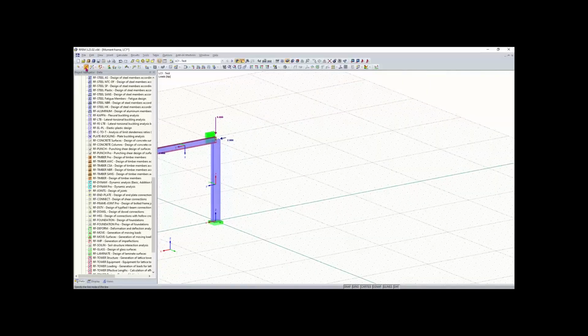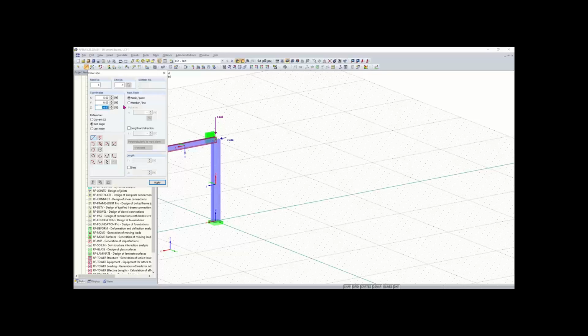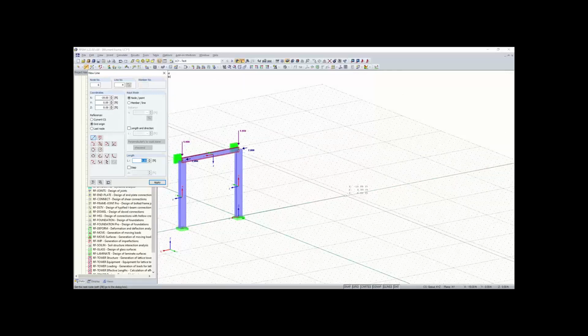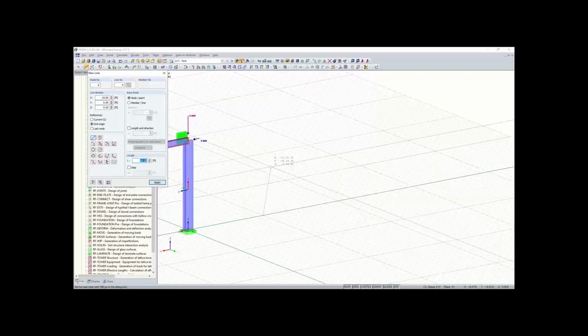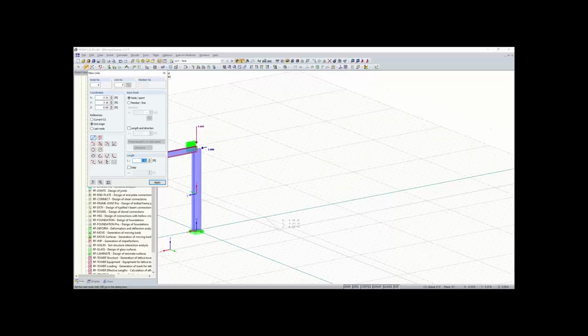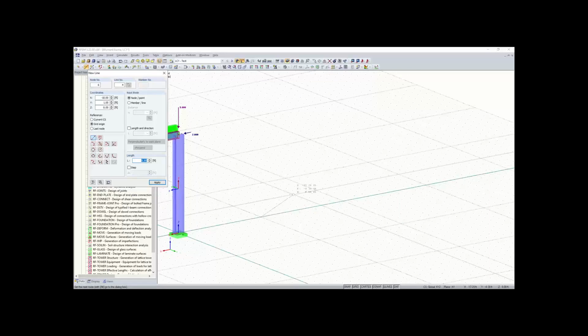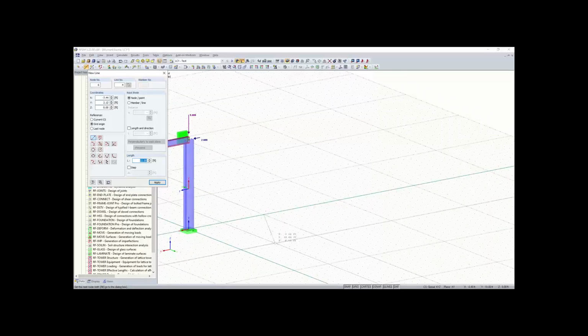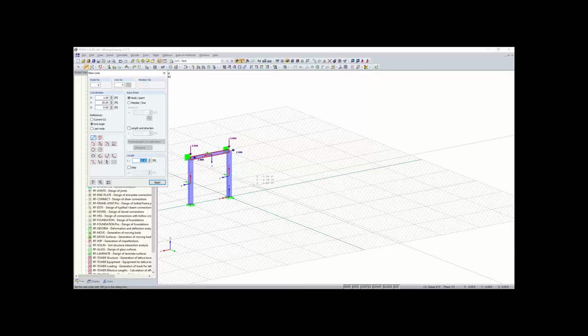So creating a new line, again, you can use this tool. If the dimensions are not accurate, I would interpret that as the length not being accurate. I think just showing how to modify node coordinates or dragging and dropping, there are multiple options. Right now, when you click, the cursor is always going to draw the line in the work grid that you have placed, and right now mine is in the XY plane, so I'm going to draw in the XY plane.